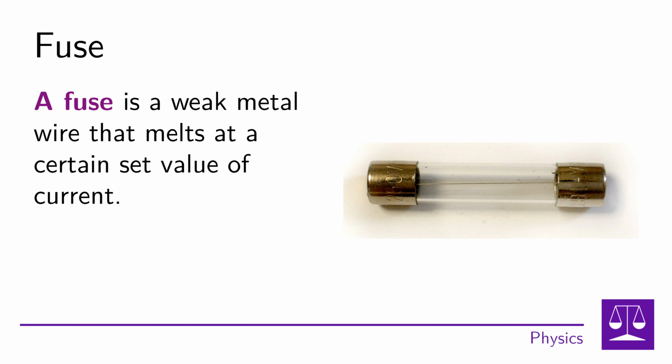Now let's talk about the individual components. The fuse is made of a thin metal wire that will melt if too much current flows into the circuit. When the fuse melts because of the high current, it breaks the electrical circuit and protects the other components of the circuit from damage. It is therefore a controlled burnout of a conductor in a protective enclosure that protects the surrounding area from fire. Fuses come in a variety of sizes and types.